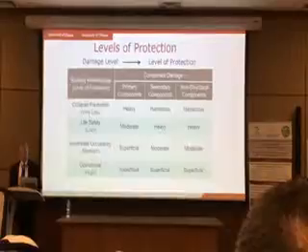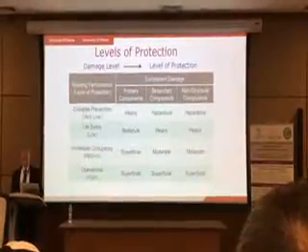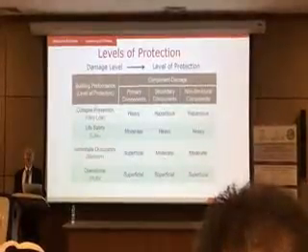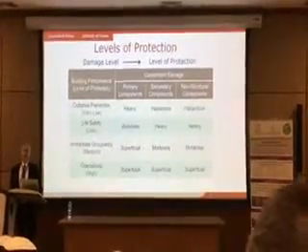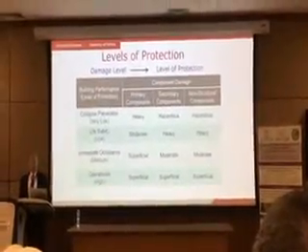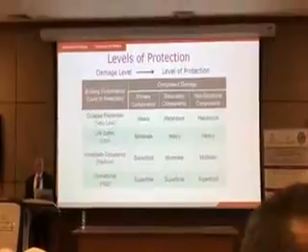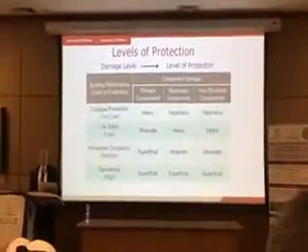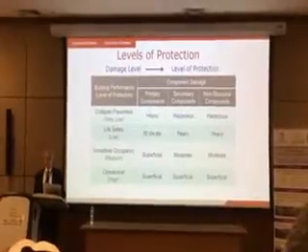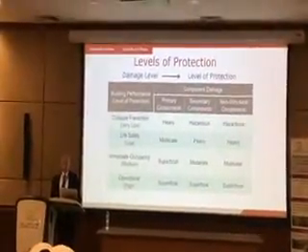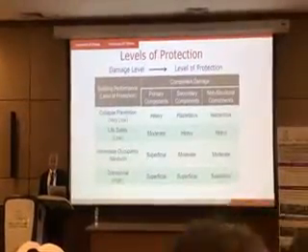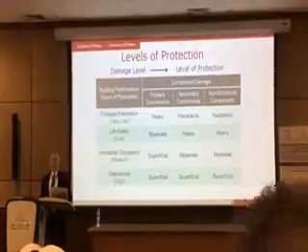So let's say your owner said, I want life safety, and I don't want anybody to be killed, then you have to design it for low level of protection. Your primary members should be moderate, which means B2. Your displacements have to be less than B2. Your secondary components can be heavy, it could go up to B3, and then non-structural could be heavy as well.